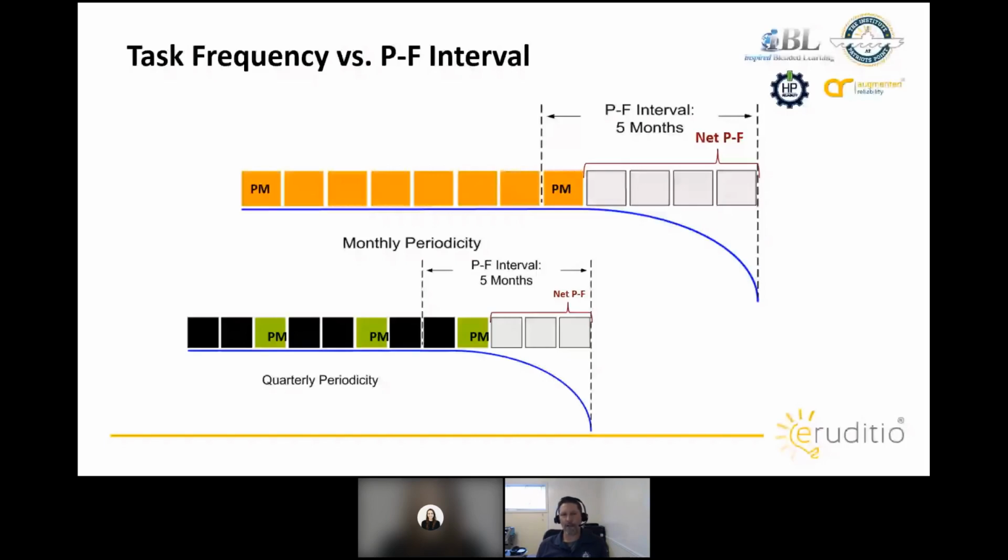Now, however, if we have a very small, high-speed spindle bearing turning at, say, 10,000 RPM, and we start to have a minor defect in that, chances are it's not going to last very long, right? We're talking hours, maybe days.